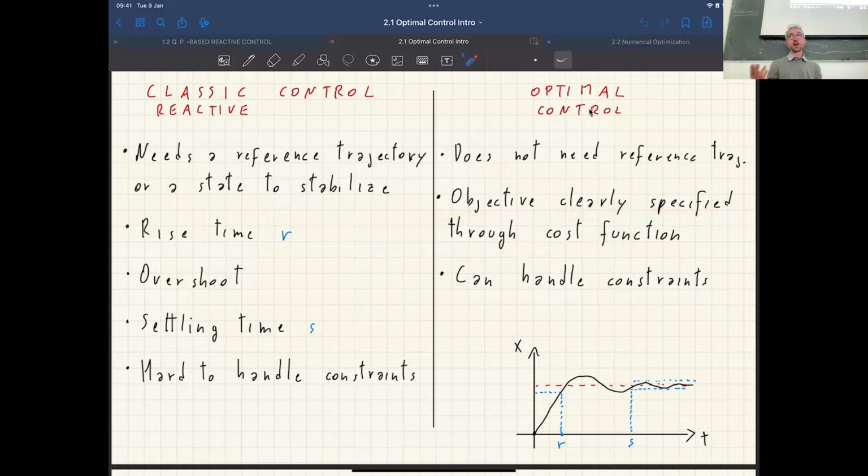That's typically going to be a function of the state and control inputs of the system. And the solver is going to find a motion that minimizes that cost function, so it's going to be optimal for that cost function. You can generate minimum time motions or minimum energy motions or maximum speed motions, whatever you want to optimize, just put it in the cost function and the solver is going to minimize it or maximize it.